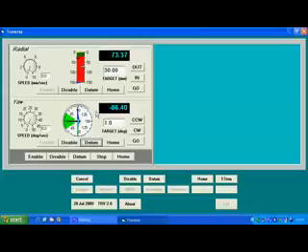That angle allows us to set a 0 point so that we can increase the speed. We'll set the target to 0 and we can press go, and again it will now go to 0. And we can find that the axis is now mid-travel, and there are alignment marks on the yaw axis to set the 0 point. A reasonable maximum speed is around about 30 degrees a second. Again, you can move quicker than that if you really want to, but there isn't usually any real need to do that.